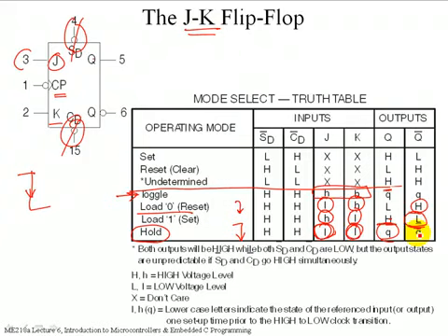Question? Yes, Indu. What? We're ignoring those. Next time I'll take them out of the table. When you buy a discrete flip-flop, it will have these extra pins that allow you to force the output, the Q, to be a 1, or force the output, the Q, to be a 0, independent of the clock pulse, so that you can initialize it into some known state. Okay? We're not going to design with these things. And having the set and reset inputs on functional schematics is relatively rare.